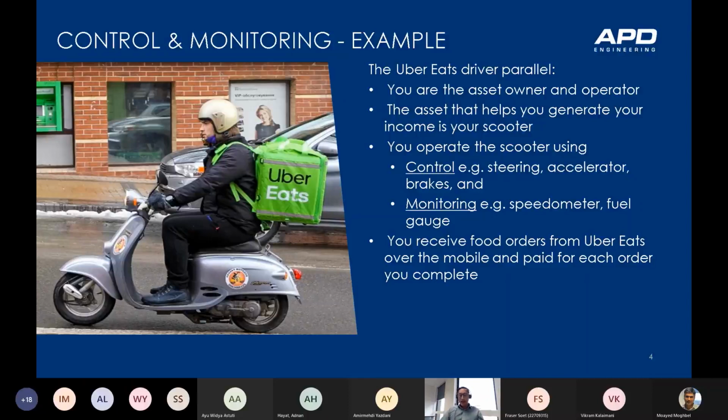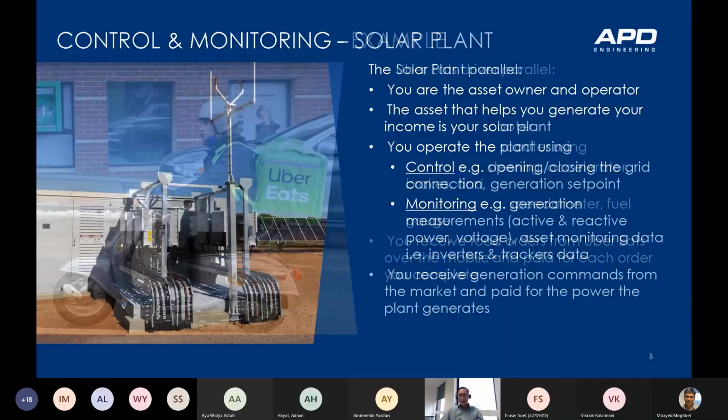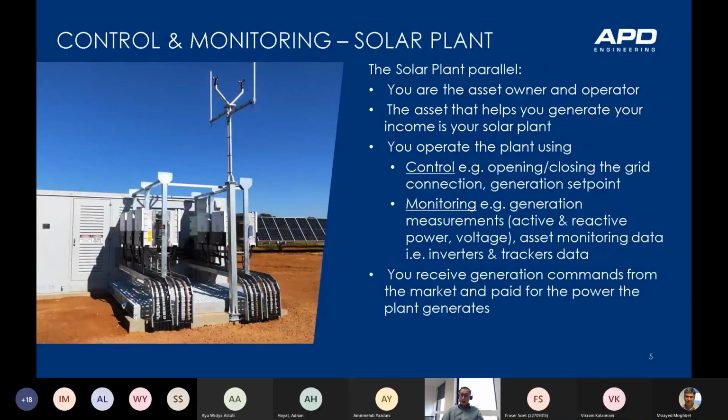So I'm drawing a parallel of that to a solar plant. So you are the owner and operator of this asset, this solar plant, which helps you generate your income. You operate the solar plant using control. You open, close the grid connection, send it generation set points, whatnot, and you monitor it. You know, generation measurements, like active, reactive power.